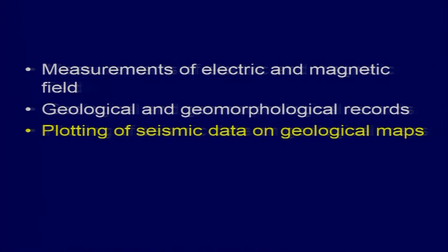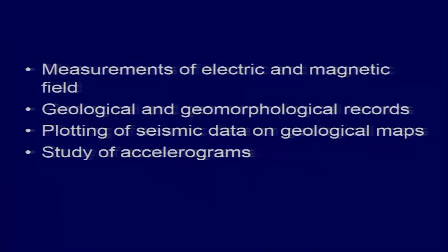Plotting of seismicity data on a geological map is a preliminary exercise. Usually we try to understand the pattern of this seismicity, whether it is aligned along one particular fault or it is diffused seismicity. If it is aligned along one particular fault, then one can say that these earthquakes are triggered along this particular fault, and there is a likelihood of a bigger earthquake in future. And then, study of accelerograms.